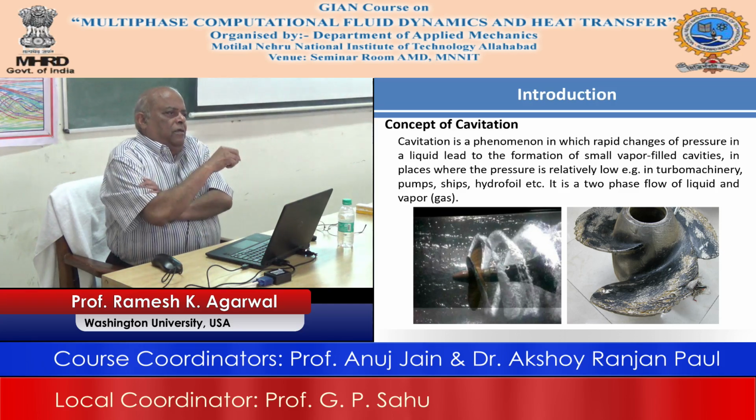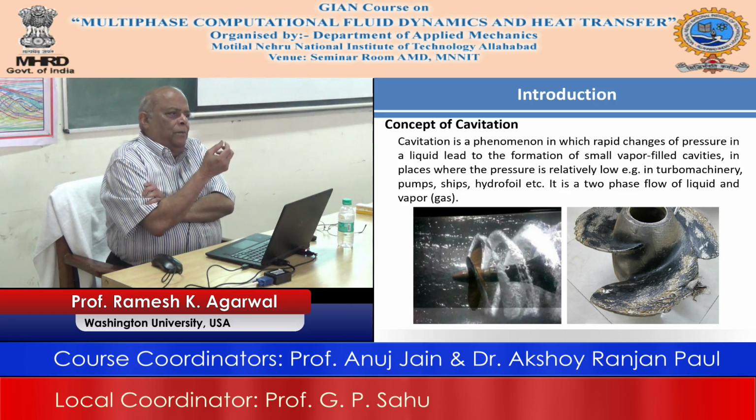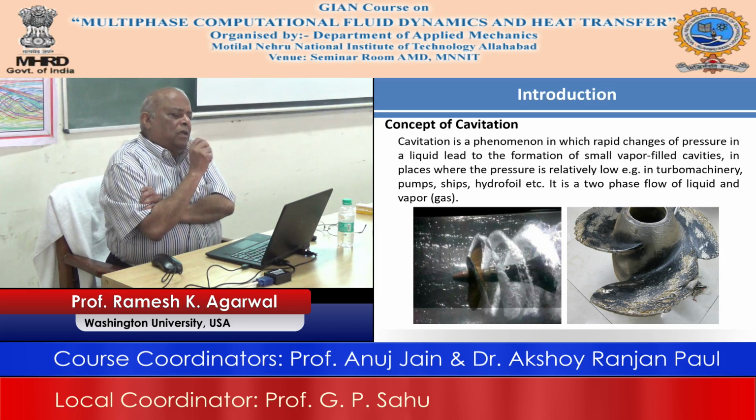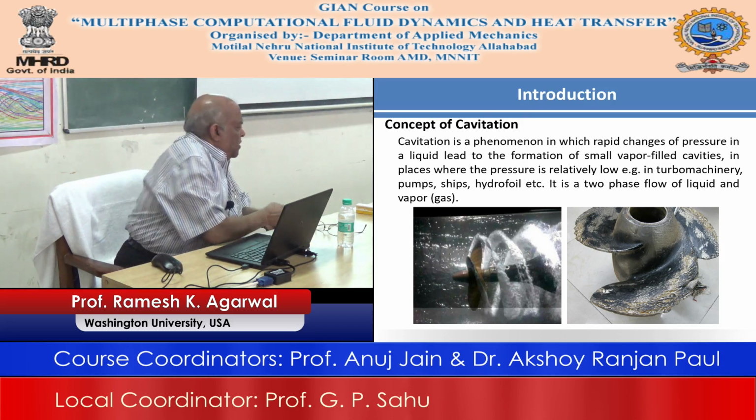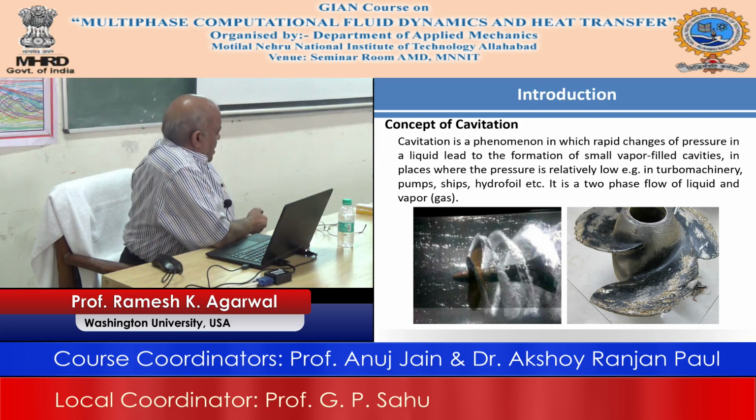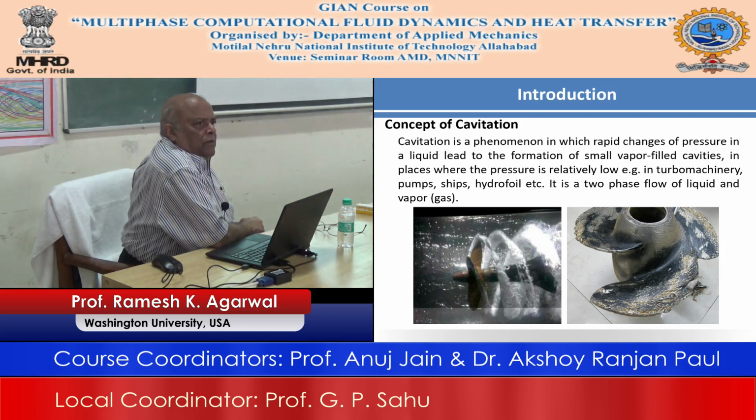And the reason is that cavitation occurs if you have a liquid, and in that liquid the pressure becomes so low that, at a certain temperature, let us say even at atmospheric temperature, to sustain itself the liquid evaporates into small bubbles. So what you see here is a very common picture: in rotating machinery, you see bubble formation.